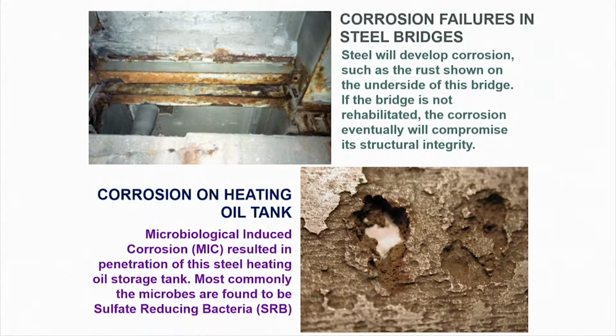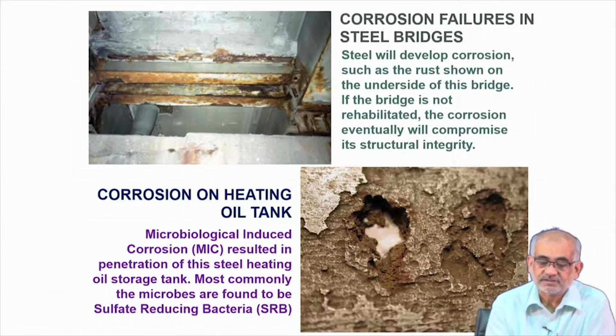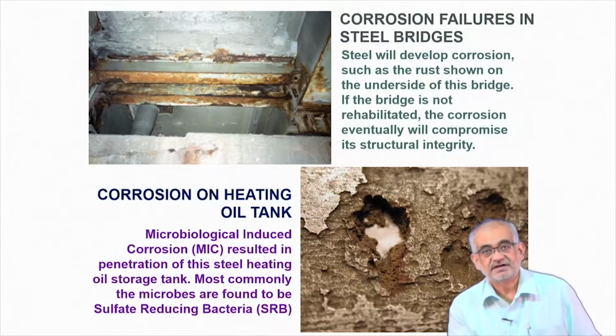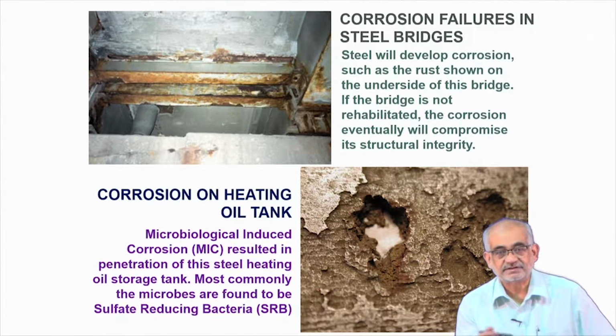In all these cases, I'm just giving you examples which are all from practical cases. Say, for example, a huge bridge over a river or over a railway track or over certain distances, and you have multiple members, and it cannot be a monolith. Obviously you have joints, and these joints could be welded joints, could be riveted joints, and in fact you may have joints between two members which are compositionally not exactly the same. And I told you already that there is always a danger if you have compositionally different members joined across a particular point, because now these two members, because of their compositional difference, can have different electrochemical potential, and as a result one can act cathodic in comparison to the other, which may be anodic, and the anode portion will start leaching or dissolving faster. So we need to prevent rusting on the bridges, and that's why you'd find all the bridges are painted, and painted not just once, painted periodically.